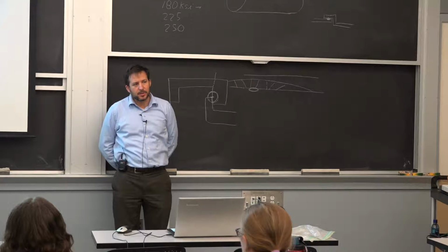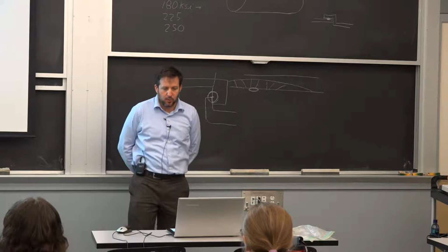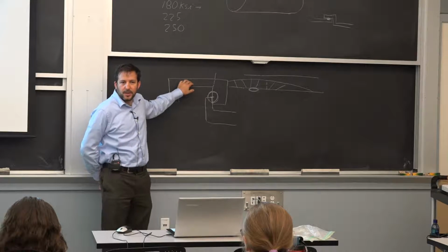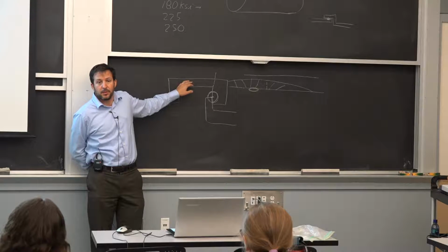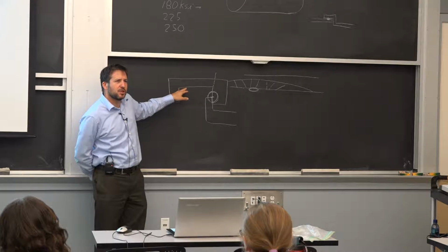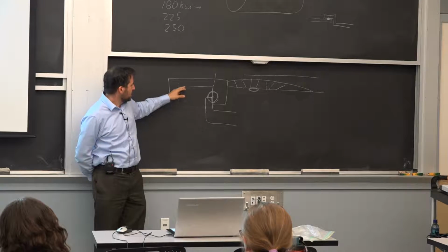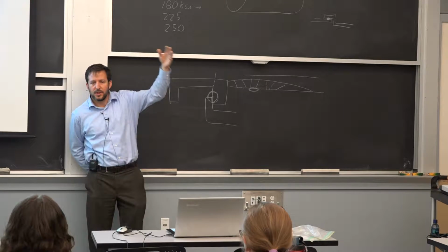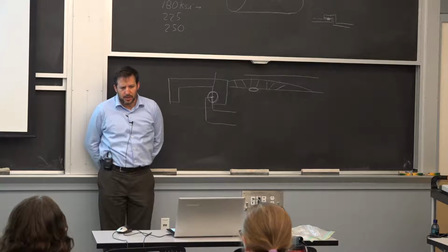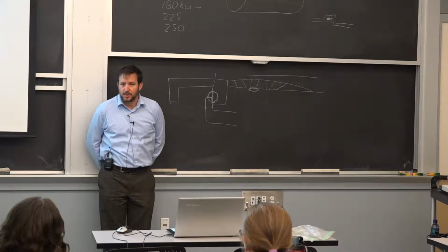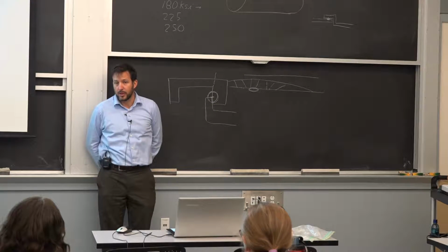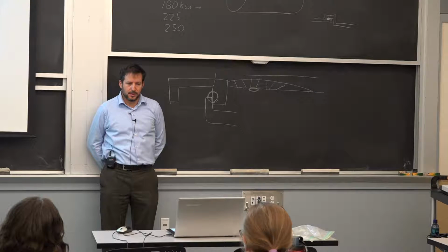I wanted to bring out some more examples of where we used this, and this was also quench and tempered because you don't need to weld it. It was a single piece that, I believe, was machined and then formed into this half clamp shape. And part of that reason is probably just volume. So if they were making a large quantity of the exact same shape, they would try to forge it. But this one was machined.